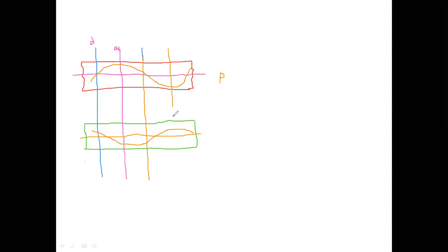And again this is the quadrature axis. I am drawing it with the same orange color. Once it is the direct axis, again it is a quadrature, again it should be a direct axis, like that, not with the same value of direct and quadrature; it should be changing. With respect to this, this is the A1 value, which is the peak current density of a sinusoidally distributed current sheet. A2 is the peak current density of the secondary side.